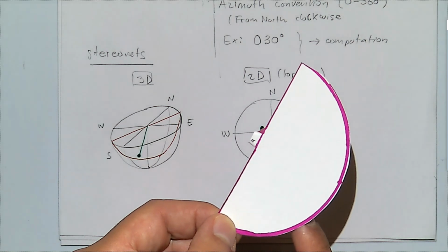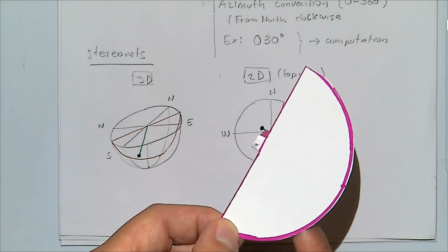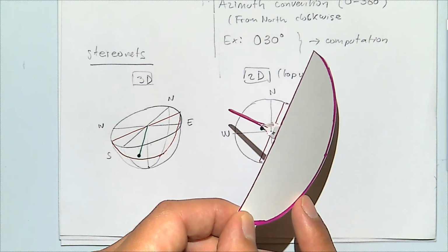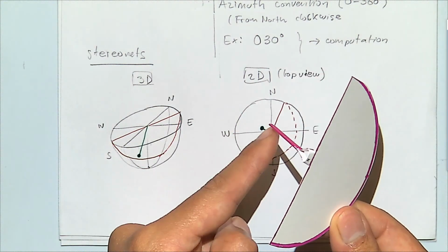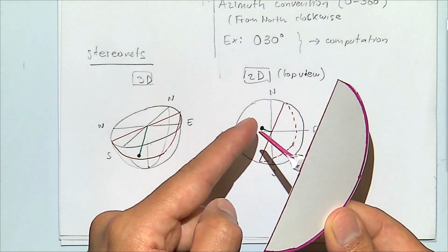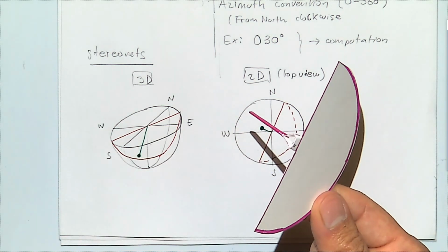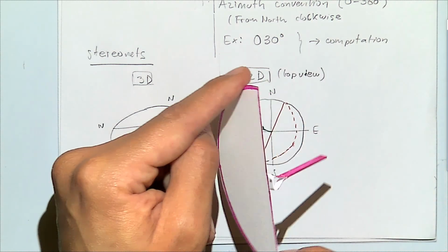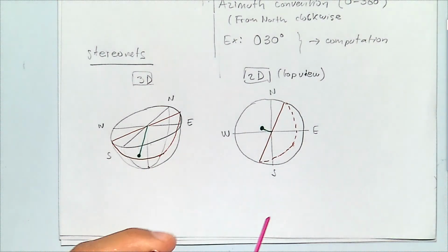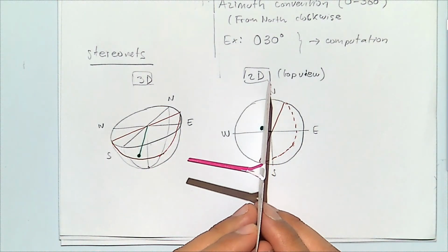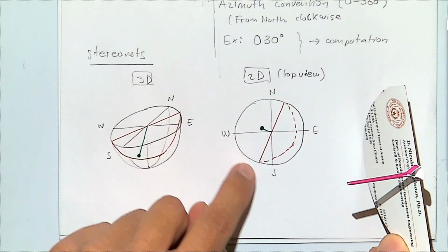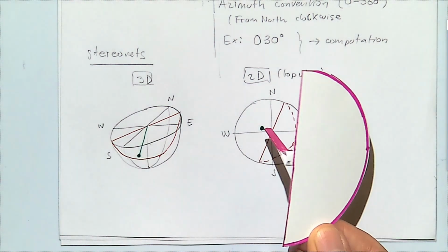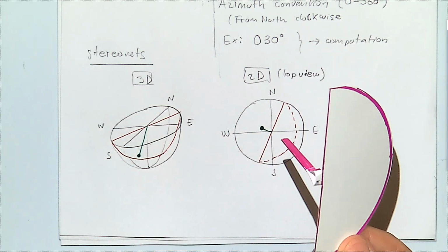And for this one, we said the dip was 40 degrees. So let's say somewhere over here. So what we want to plot is the tip of this line and where it hits the lower hemisphere projection. But just with one point, we can represent any strike, any dip. For vertical fractures, the point is going to be in the outer edge of this circle. For horizontal planes or close to horizontal planes, it's going to be closer to here.